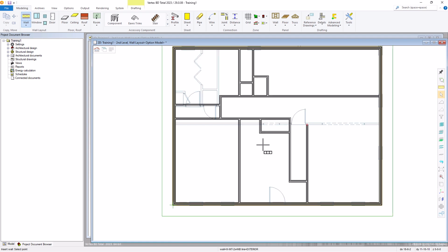So we've added these walls manually using the Q reference. We're going to go over one other feature called constraints. We have a few more walls over on this area that we need to add. And I'm going to show you how to use constraints so that you can rough in some walls and then add constraint dimensions that will be used to adjust the walls to their exact locations.